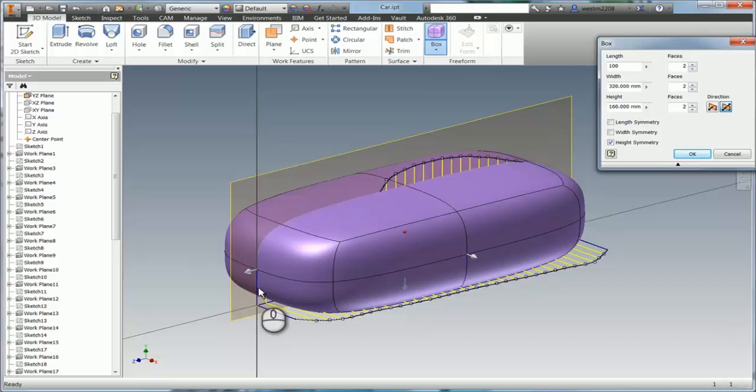I don't know if you can see the difference. There's now a grey line that runs around here, which is going to say whatever you do on this side, it's going to copy on the other. Now what's very important with freeform modeling is if you choose symmetry now, you can't delete it afterwards. So if you choose symmetry now, this whole freeform block will be symmetrical forever.